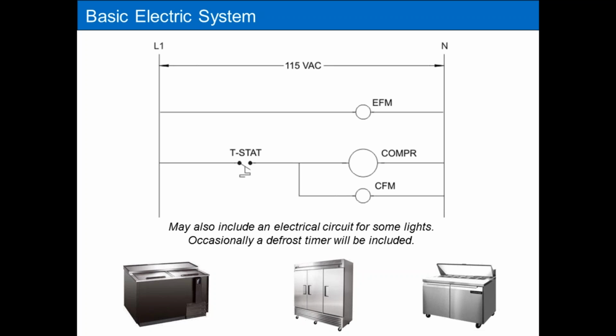Now, included in some of these electrical systems, you may see some lighting systems, a general lighting circuit, and every once in a while too you'll also see a defrost timer. A manufacturer will design their system to mechanically shut off the compressor by time to assist the defrosting of its evaporator. So you may see some wiring diagrams with a defrost timer included. But what I'm showing you on the screen is by far the most common wiring scheme out there.